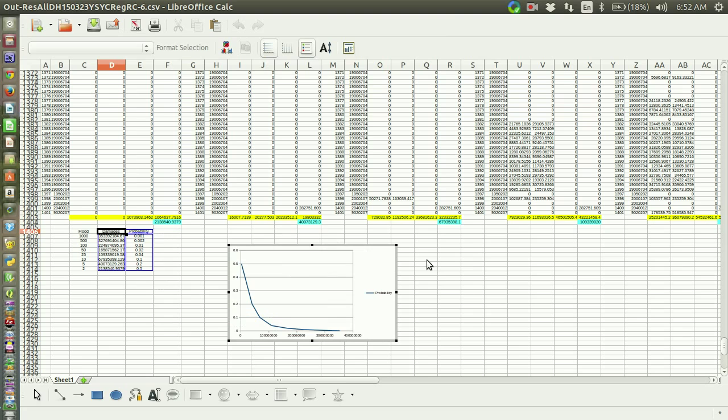So in this case now, this is your probability damage curve as per the flood frequencies we've run for this condition in Drumheller. You would then take this curve and do some more processing to generate the average annual damages.